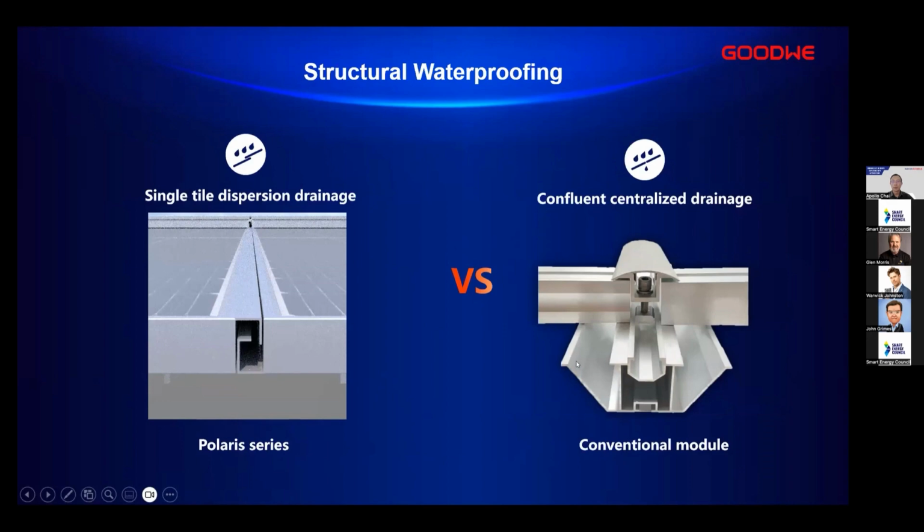it is required to have this kind of open water drainage built in. The problem with this open water drainage is that, in the long run, the leaves, dirt, and branches that drop from the trees will accumulate inside the chamber. And in the end, the water will come out and leak to the ground.